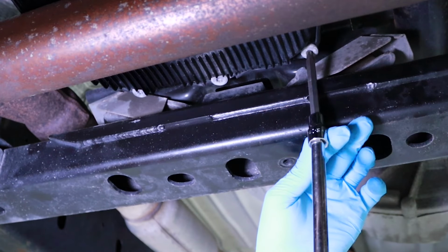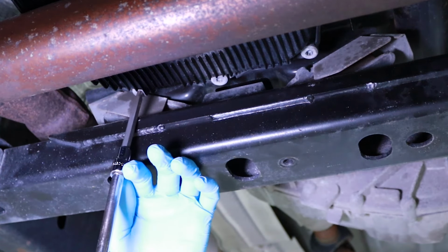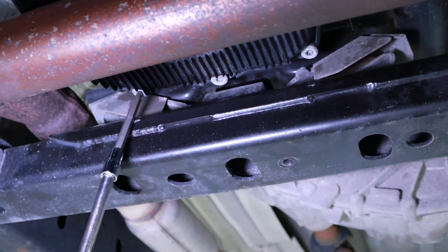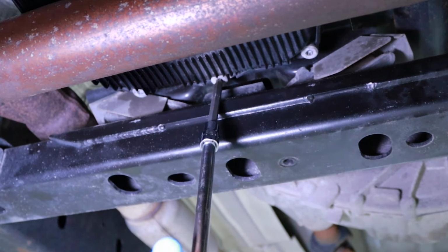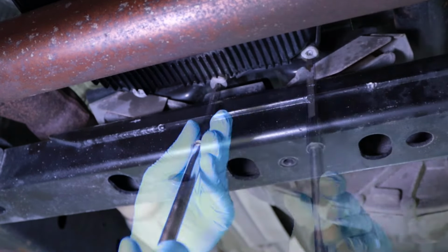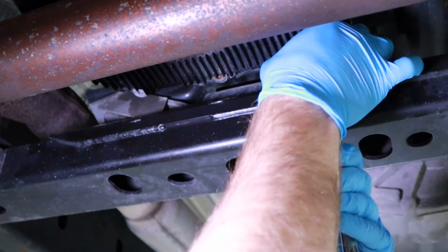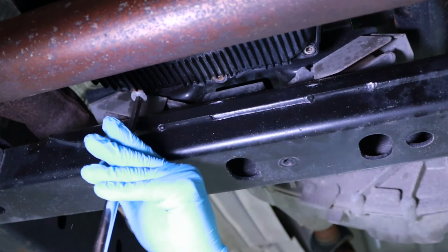The rear 3 transmission pan bolts are best removed using a long 5 to 6 inch T40 Torx bit socket. This allows better tool angle and clearance around the transmission crossmember. Remove all transmission pan mounting hardware except 2 bolts, leaving one on each side of the pan hand tight, in order to support the pan until its removal.